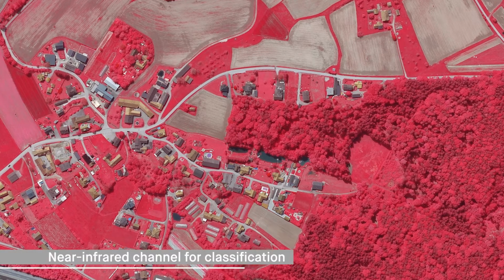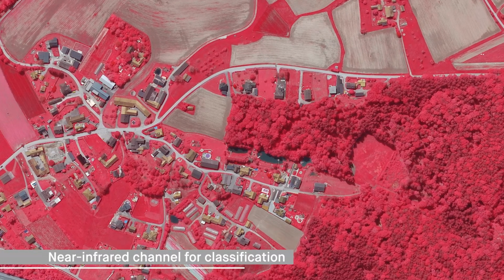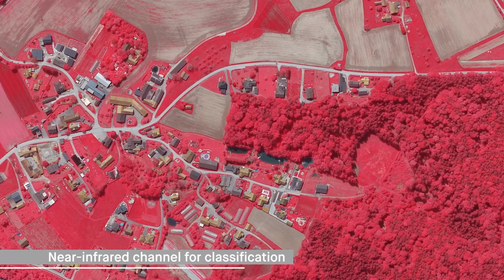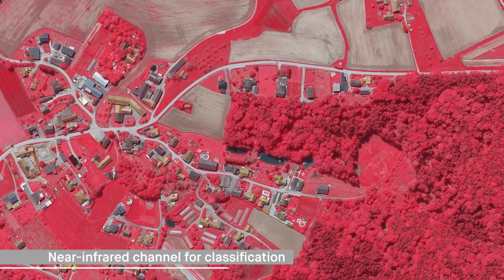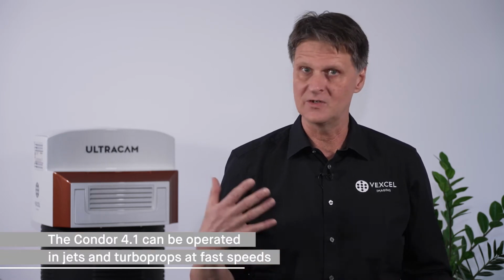In addition to the RGB and the pan channel, the camera has a near-infrared channel in a lower resolution, which supports land classification. So that is also an application that you can do with the Condor. Thanks to the very fast frame rate of 0.7 seconds, that camera can be flown very, very fast and is designed to be operated in planes like turbojets or even jets.